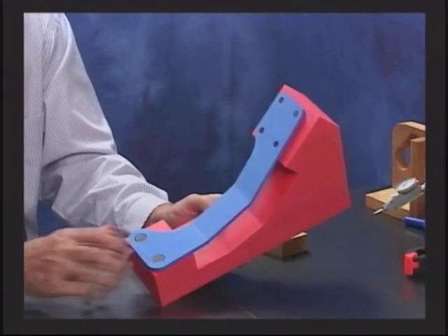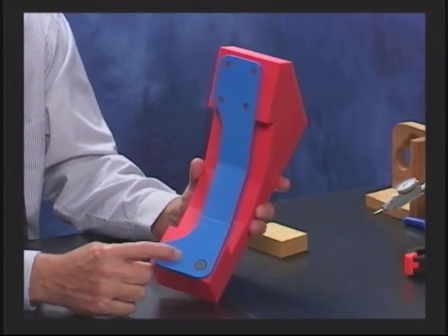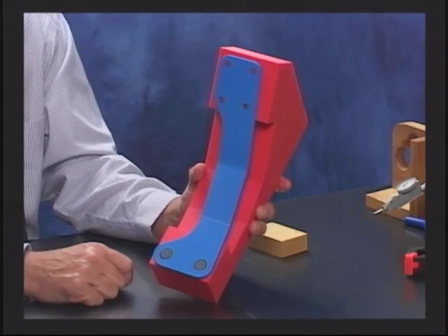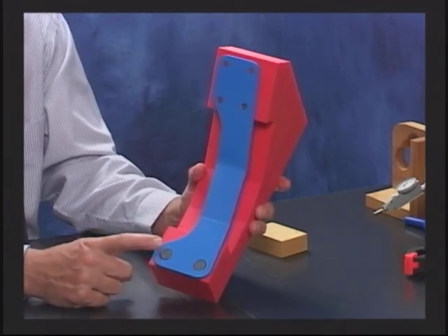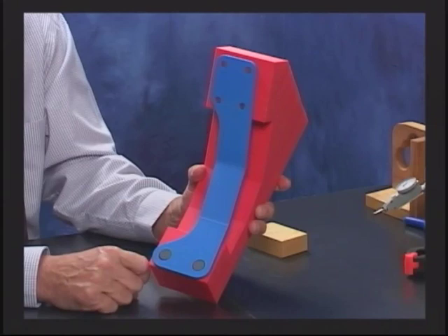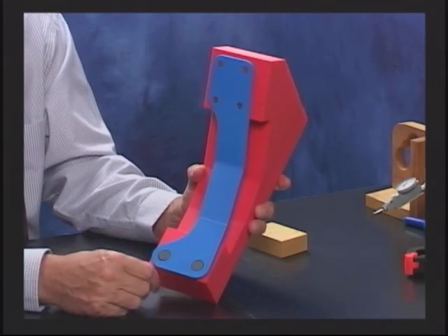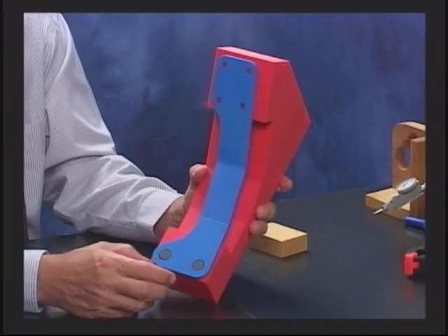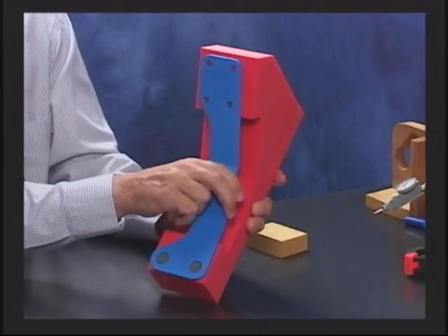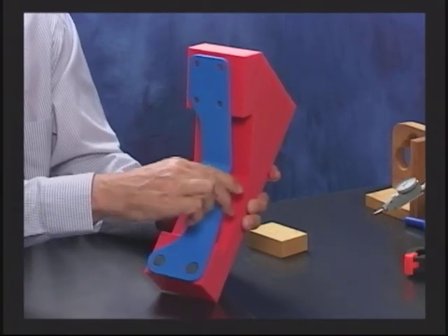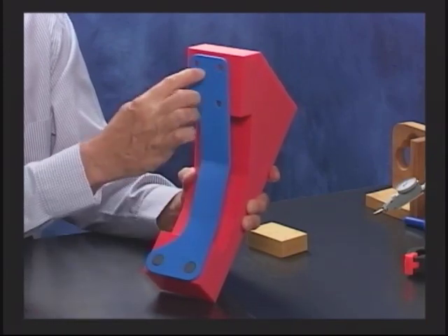Now the MMC and the datum, what that's going to do is tell us down here we have virtual size pins. And if you have virtual size pins, you have 16 millimeter gauge pin size, and the holes got a little bit larger. Remember, the holes could go, I think, up to 17.5 or 4, whatever that was. When it goes on, you see what's going to happen. It's going to wiggle around on this gauge. It's going to wiggle around on these pins. It's also going to wiggle around.